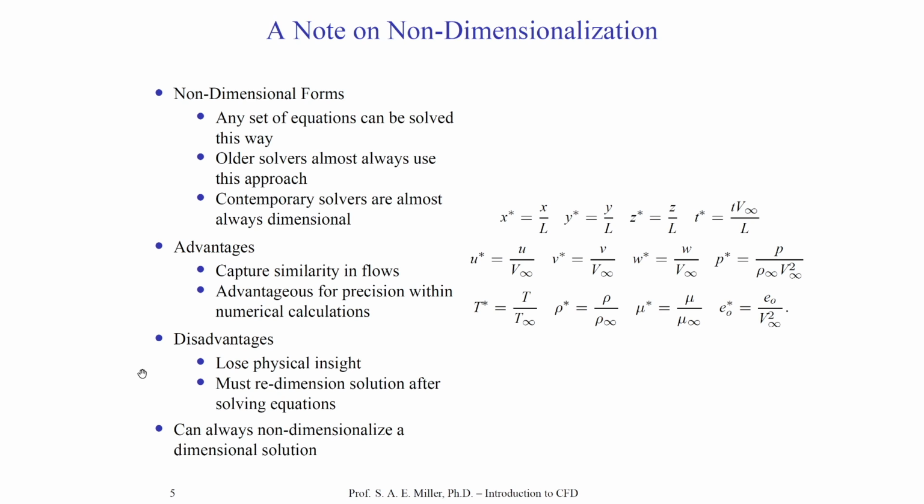But of course, if we convert from non-dimensional numbers using the dimensionalization on the right or an equivalent one, then you can recover your dimensional values. You would do this anyway when calculating actual lift and drag. This means, of course, that you must redimensionalize the solution after the solver ends if it's a non-dimensional solver. So when your solver ends and you find some field variables in a file, you'll have to know what they are. Make sure you understand their units too. This is a simple mistake many people can make who are unfamiliar with their particular solver.